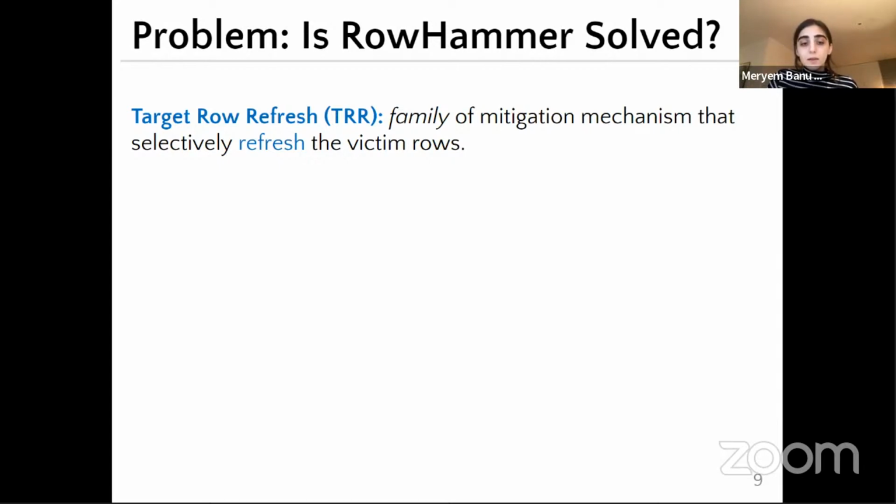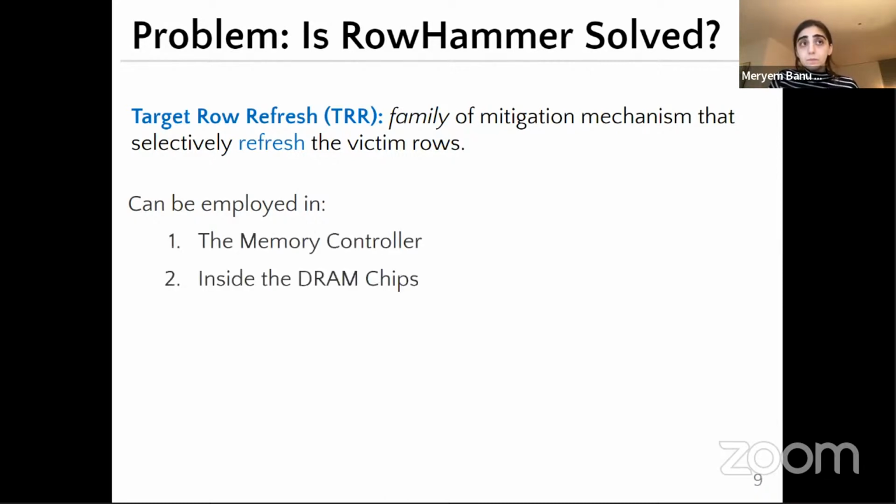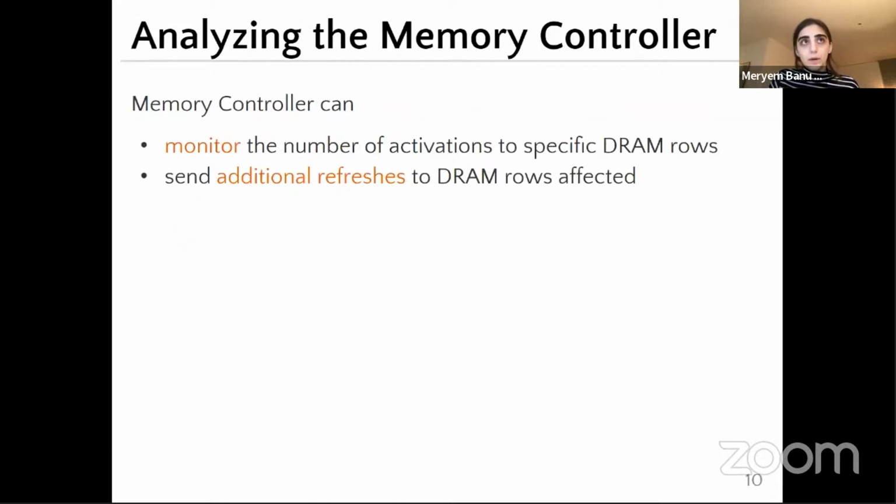The paper analyzes a variety of components with TRR implementations to develop a better understanding of the underlying TRR mechanism. Specifically, they analyze a TRR mechanism in the memory controller and several TRR implementations inside the DRAM chips. And let's start with the memory controller part.